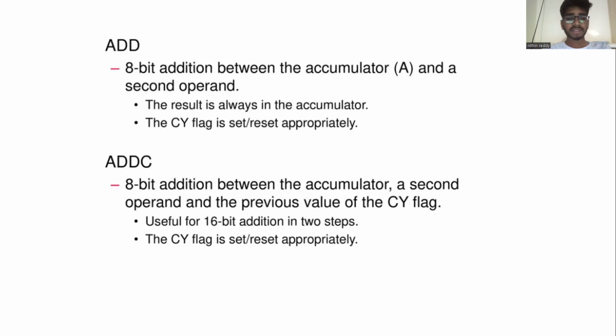4 register banks, 32 general purpose registers each of 8 bits, 16-bit program counter PC and data pointer, 4 KB on-chip program memory ROM, and 128 bytes on-chip data memory RAM.